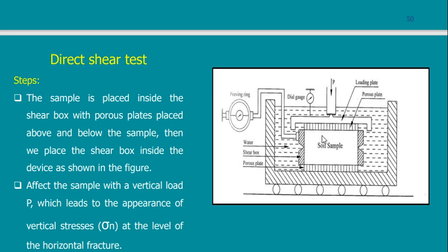My sample will be sheared, because the lower cylinder will stay in place and the upper cylinder will move. It may be a cylinder, it may be square in cross section, it's the same. What I mean is I have a soil sample with a fixed container at the bottom and a movable container at the top, and I move this movable container, ending up with shearing the sample.